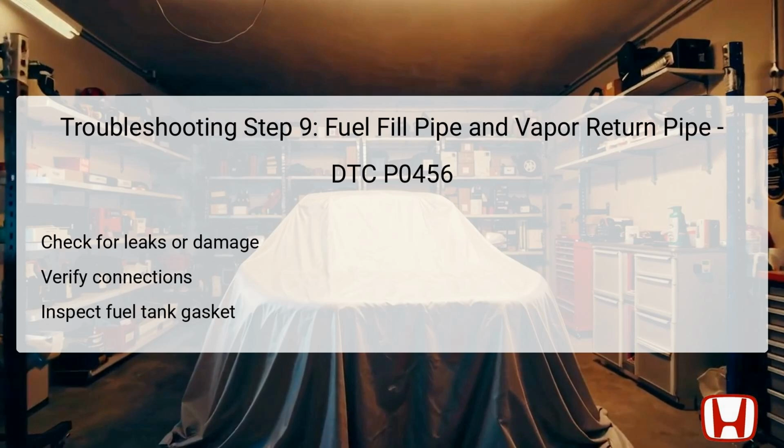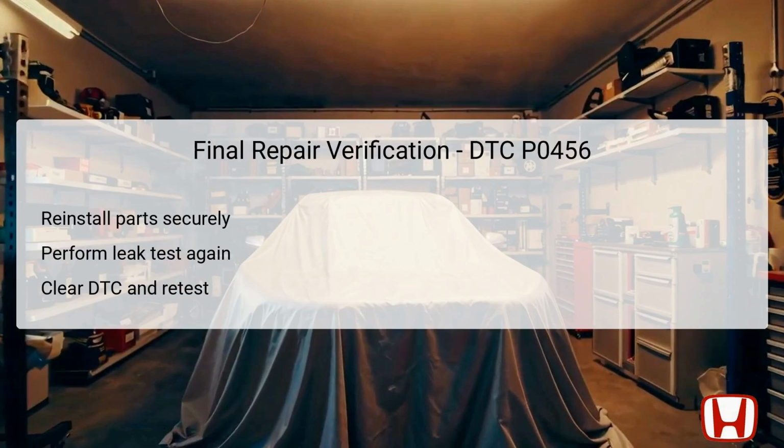If the visual check finds no issues, further testing of the fuel tank assembly or fuel cap system is warranted. Properly sealed fuel fill and vapor lines are vital for preventing emissions-related DTCs. After completing repairs, reinstall all parts in the reverse order of removal.